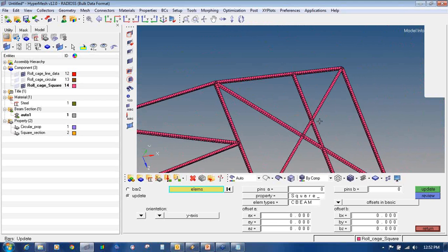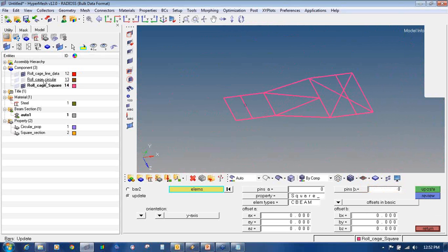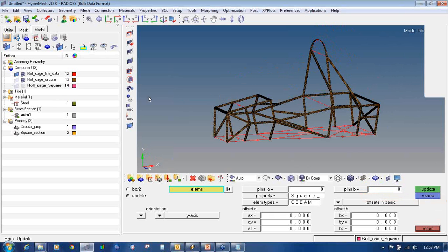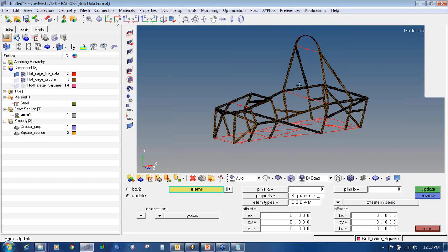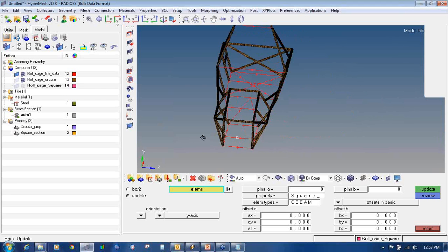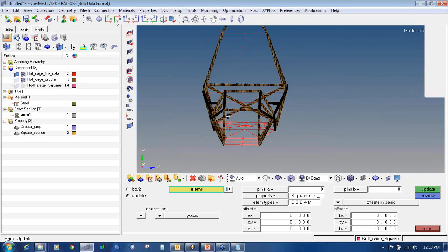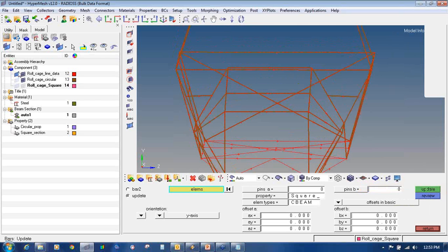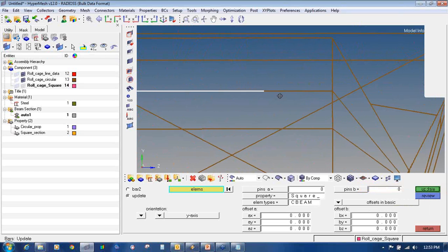Okay, here you can see. Now I will turn this off, and on the circular one, again I will go to the circular one and see where exactly the issue is. You can see these are the areas where the cross section is not properly defined. Same, the axis is Z, I have to orient in Y. So again I will move it to the line mode of the geometry and select these lines.